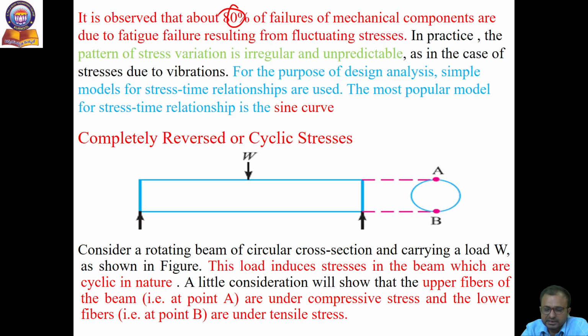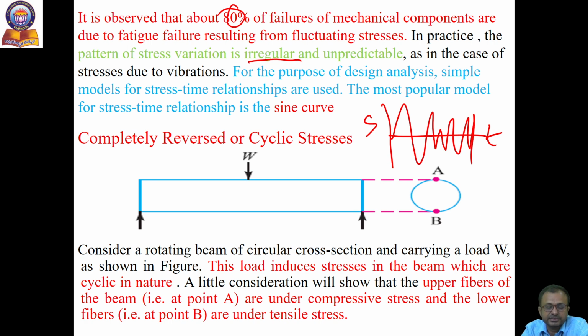In practice, the pattern of variation is irregular and unpredictable, because if you draw the stress-time graph, the variation of stress is very irregular and unpredictable. For the purpose of design analysis, simple models for stress-time relationships are used. The most popular model is the sine curve.